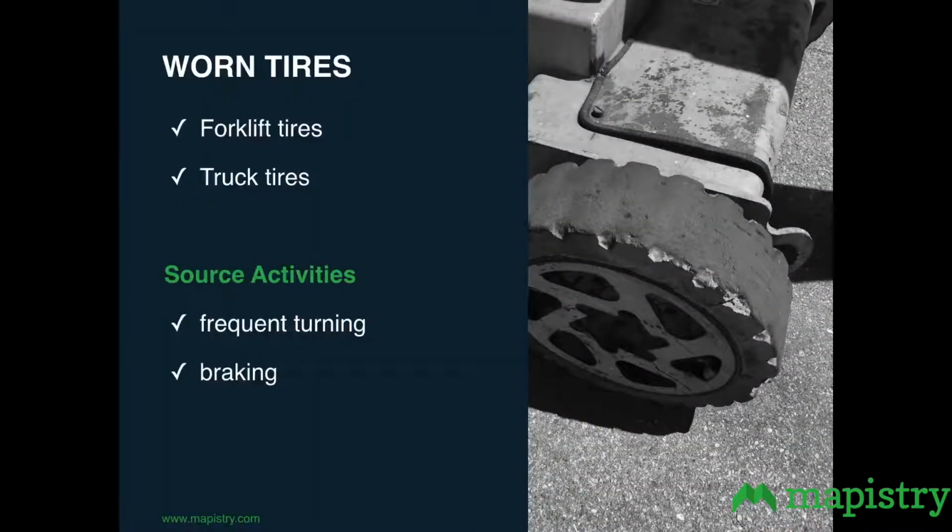The other thing is your industrial processes, or yourself. You may be doing aggregate processing, and you may have some sort of TSS from that. But it could be your forklifts: if you're turning, braking, grinding, those small particulates are getting onto your surface. We talk about it from a metals perspective, forklift tires high in zinc, but that also contributes to a TSS reading.